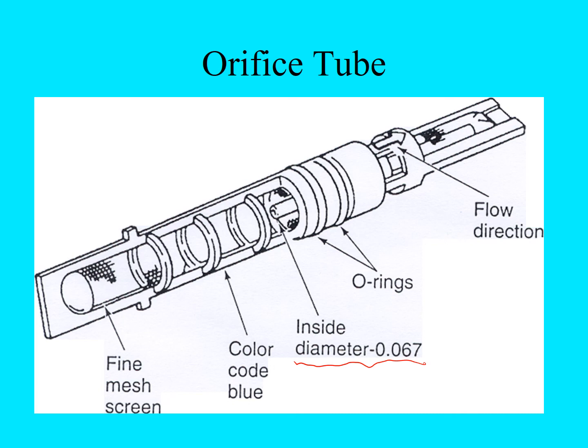Usually any debris in the refrigeration system comes from the manufacturing process, so they put a little screen there to help make sure that anything that broke free inside the system is not going to get into the actual orifice.